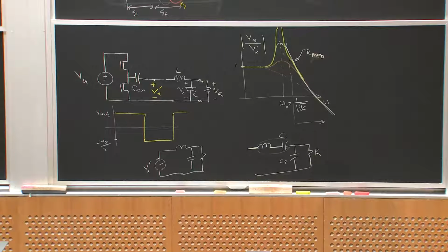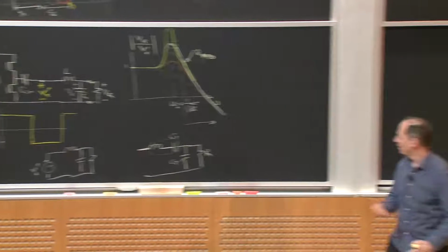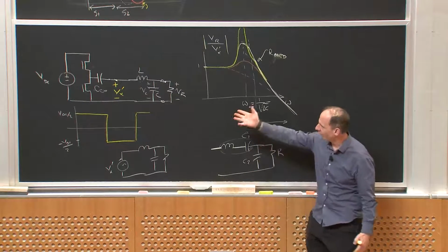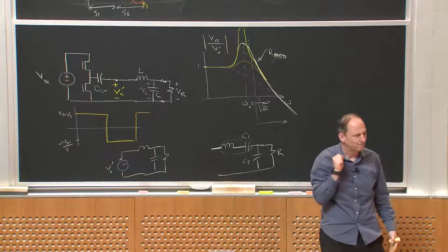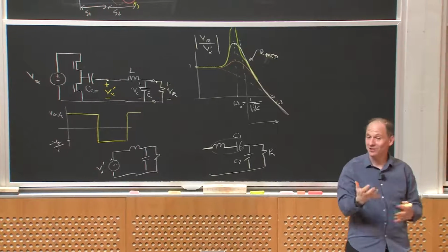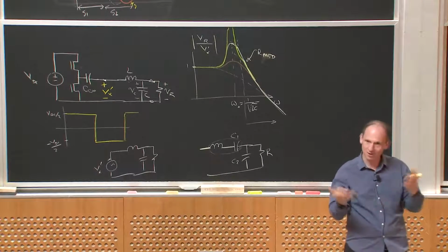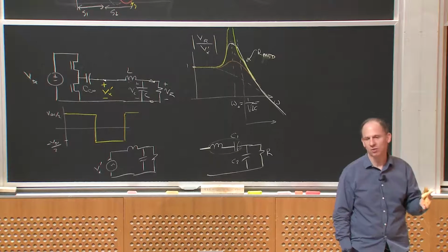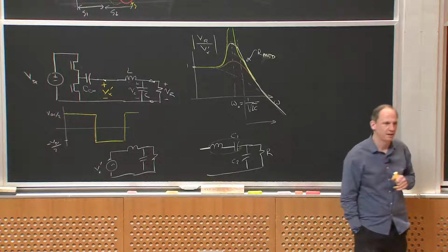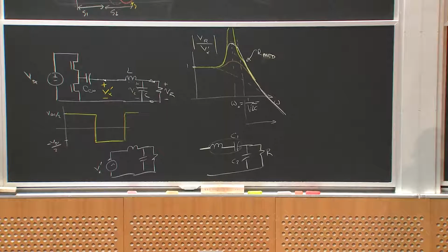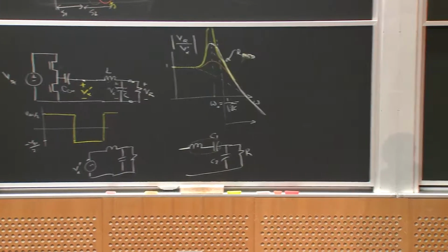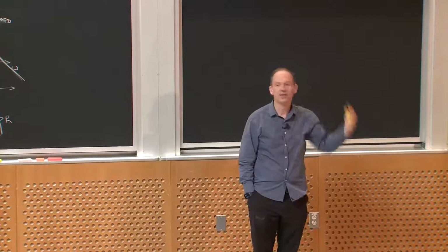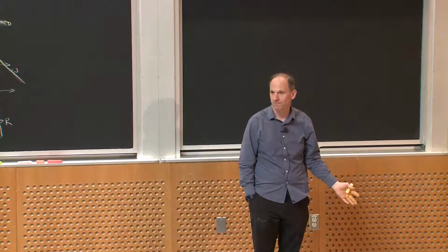That kind of network's used too to balance what happens at large and small resistances, for example. It has some sort of hybrid combination of series and parallel. You can also have LLC, where there's two inductors and one capacitor. That's another extremely common resonant network. The easiest thing to get your brain around is the series and parallel kind. There are other kinds that people use because they give particular characteristics for different ranges of load resistance or for different ranges of operating power.